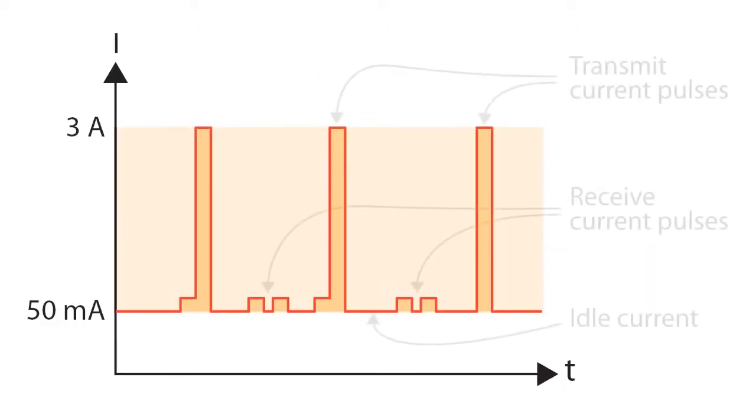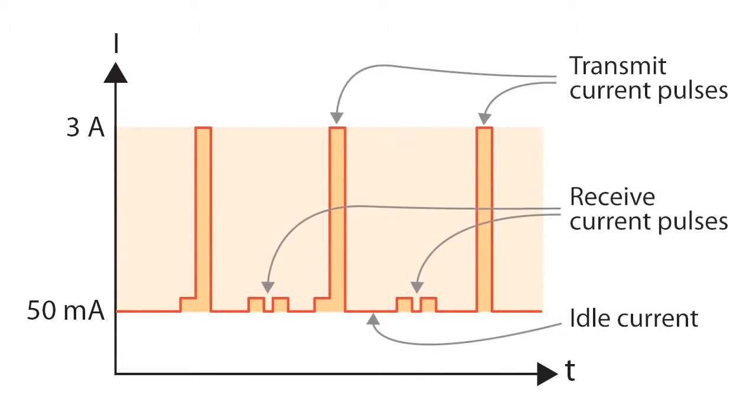Accurate measurement over an extended dynamic range is also essential for obtaining meaningful results due to the high peak, low duty cycle, and low average values typical of pulsed current drain signals. Depending on the operating mode of the device under test, the crest factor can be several hundred. High crest factors consume the instrumentation's dynamic measurement range, limiting achievable accuracy.